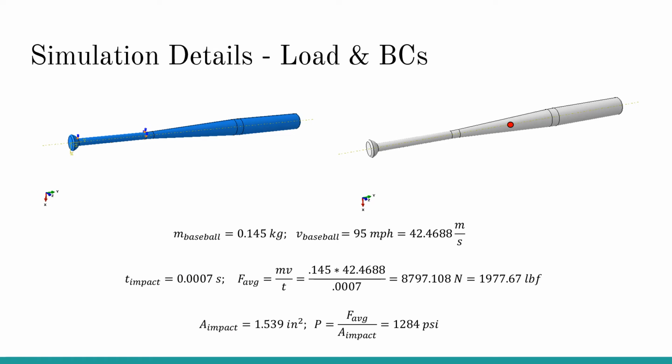My name is Sagar Patel, and I will be going through the Abaqus portion of our project. So here are the boundary conditions and loading conditions for our simulation. The loading was done through a surface pressure force that was calculated using the contact area of a baseball and a bat, which we found through our research.